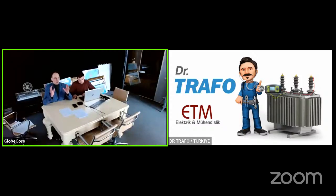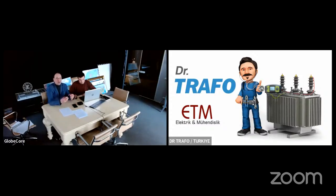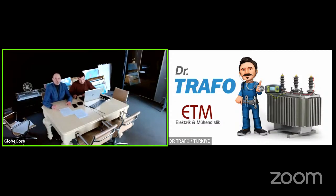If we are talking about the best conditions, for example, you did the regeneration on the on-load transformer for approximately 7 days, and you took the oil samples. The oil samples are within the limits. After 1 month, you took another oil samples, they're still okay. After 6 months, you took new oil samples and they are still okay. It means that regeneration is done properly. And probably you will need to make the new regeneration after 5 years or maybe after 10 years.